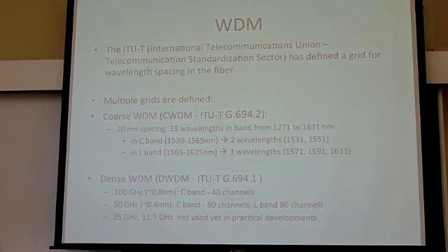Then there are advanced WDM grids, which use different types of components, and they are defined in gigahertz rather than nanometers, but this is roughly what it's about. You can have 100 gigahertz slots, or 50, which is half of it, and which one you use depends on the technology. At the beginning, they were using 100 gigahertz because the components were not good. Then they started using 50, and now they don't know what to do, because if they want to go faster than 100 gigabit and so on, they can't keep squeezing it. They have higher order modulation, but it's not easy. So you basically need to enlarge your bandwidth again.